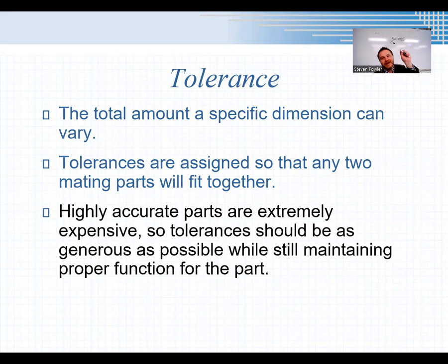If that's what it's supposed to be, I guarantee you we could put a micrometer on it right now and measure it. It's not going to be 0.25000. It's not going to be exactly a 1/4 inch. It'll be close. It'll be in the ballpark. And the tolerance specifies how close to that 1/4 inch this can be to still be functional. So it'll still interface with any cap that we want to put on it. So I could take the cap off this black pen and swap it with the cap from this blue pen, and I guarantee you they're interchangeable, because appropriate tolerances have been set for the same make of pen.